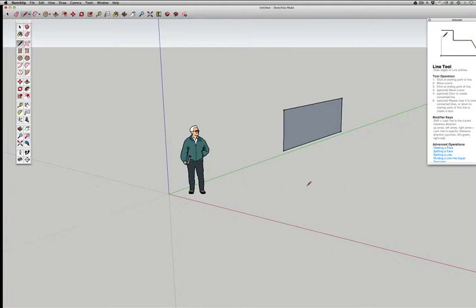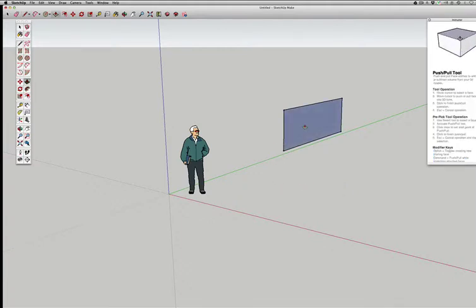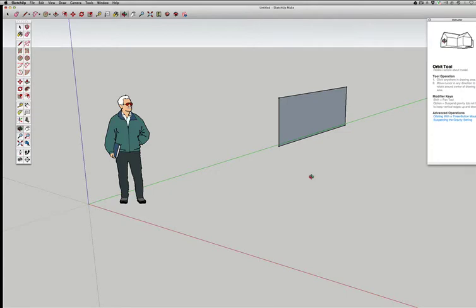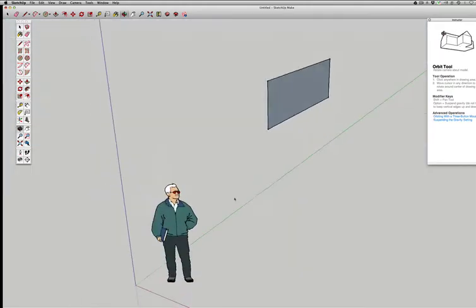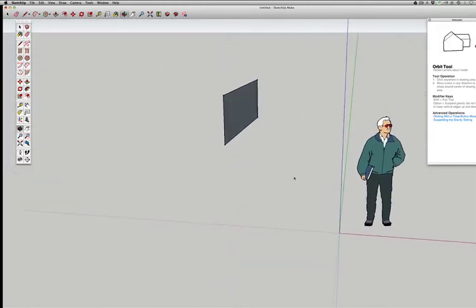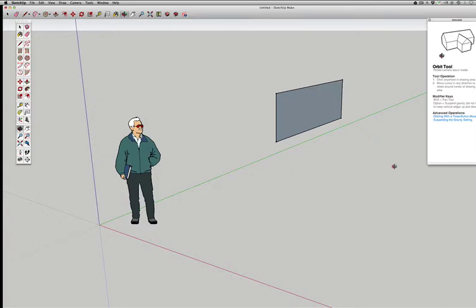Just so you can see what we can start doing with this, we can have all kinds of fun with it. But what I want you to see is this is two-dimensional. Hit the O key for orbit, or it's this key up here. You'll see it's called orbit. It'll allow me to move around. Now, I need everybody to watch me, please, because what I'm going to show you is kind of weird when you start doing it.